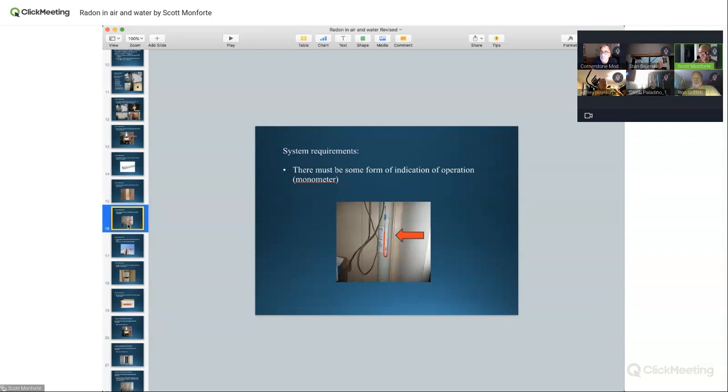When it's an old house and it's real tight soil, and also a fan can make it draw up more, it could be up to 3, 4. So that tells me a little bit about the soil. Sometimes it's an old house and I put it on and it's only doing like a 1.5, and I'm like, okay, it's moving air.